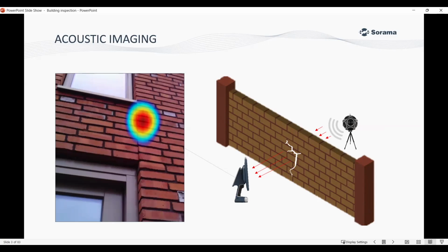On the other side, with an acoustic camera, you pick up those sound waves and visualize them. Because physically sound travels through air particles, you know for a fact that every sound leakage you can visualize corresponds to an air leakage as well. It also shows a direct fracture in the building, so it can also be used for water leakage applications.